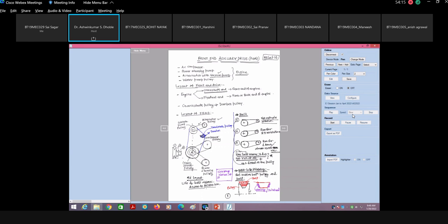At start of vehicle, that is, when you crank it for the first time, suppose your vehicle has been in the parking slot overnight, and then next day morning you start your vehicle and you hear the chirping noise, a noise of very high frequency which is very unpleasant. If you hear such noise, and this noise disappears after a few seconds of starting the vehicle, then that is the sign that 100% slipping of the belt is going to occur in the vehicle. So you need to carefully